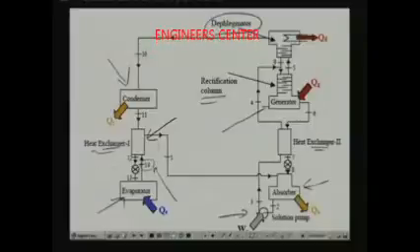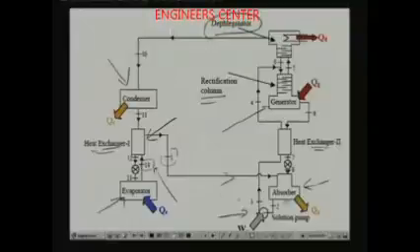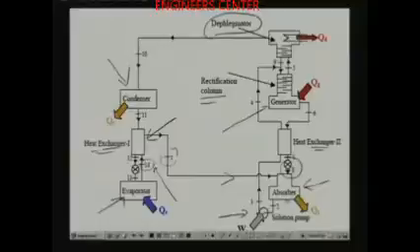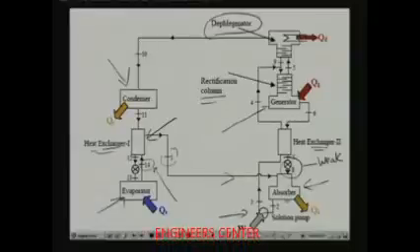So, what comes out of the heat exchanger is a superheated vapor still at low pressure. This superheated vapor now enters the absorber. In the absorber, it comes in contact with the weak solution coming from the generator. Weak solution here means weak in refrigerant. This weak solution and ammonia vapor coming from the evaporator come in contact in the absorber, and the refrigerant is absorbed.